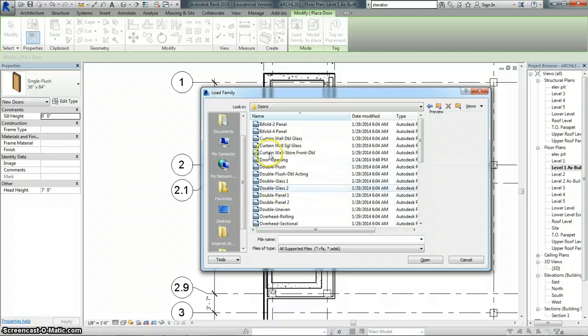And what's nice is you can go through here to, like we said before, curtain wall doors are really only for applications to changing out panels in the curtain wall. But some of the other doors are bifold, double door openings. And this is the other one. You should have door openings. Those are if you just have a doorway that has no door on it, but it's just an opening, so they also have to specify that, and we'll actually do that for this video.